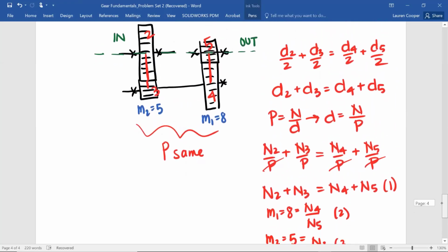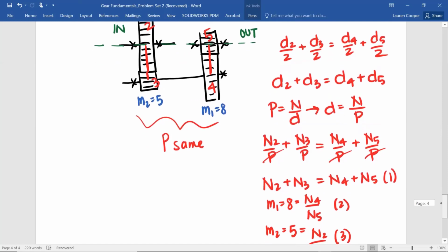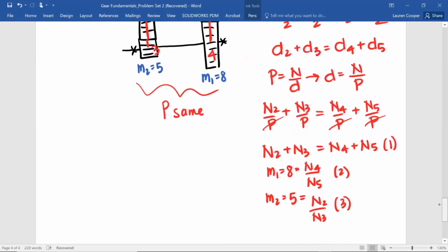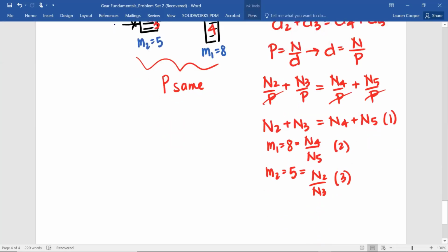And we're going to do that by specifying the minimum number of teeth of the pinion in the limiting stage. So the way to think about the limiting stage is whichever stage has the higher gear ratio. So in this case, it's this M1 equals 8 stage.